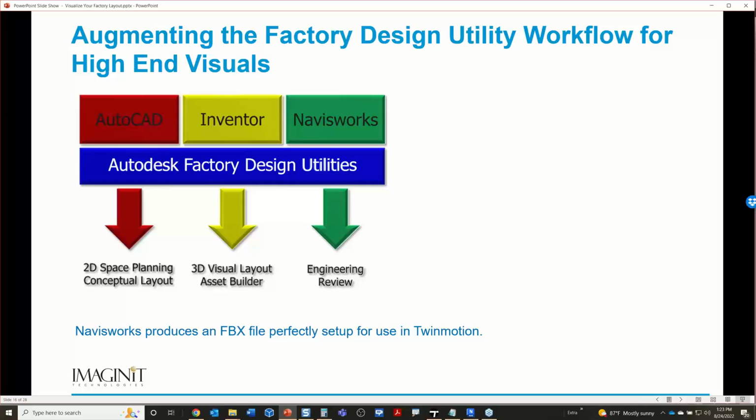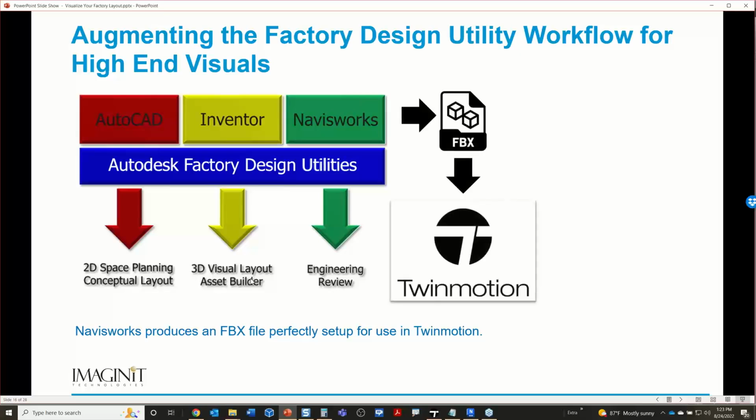Navisworks holds the entire project. And usually, honestly, in my life to this point, Navisworks is where I generate my graphics from, because everything's in Navisworks at the end of the day, and Navisworks has a nice video generation capability, quite useful, and that's where I generate most of my animations and most of my visualizations to this point.